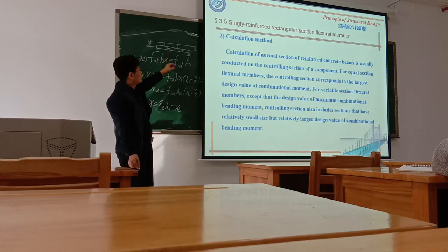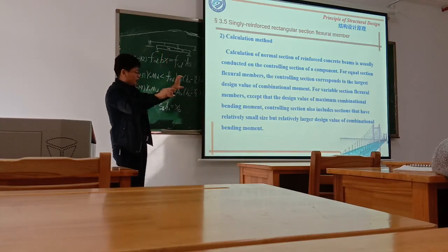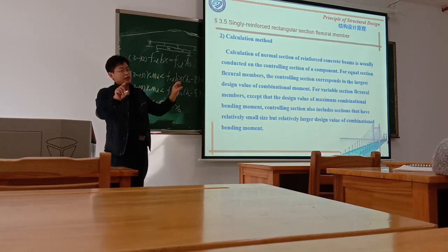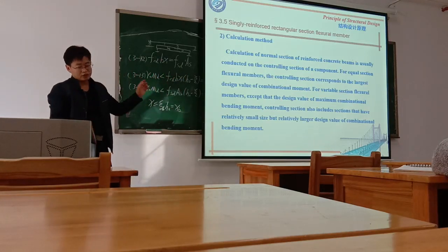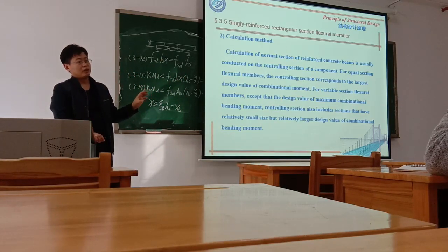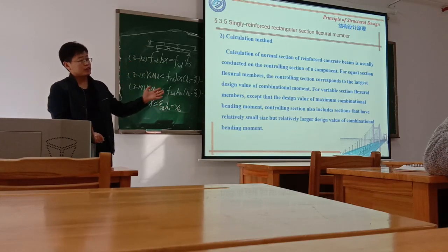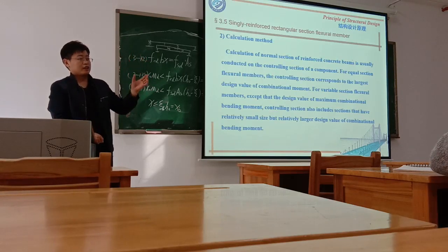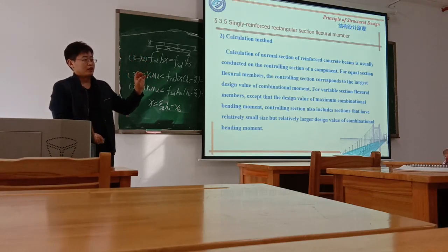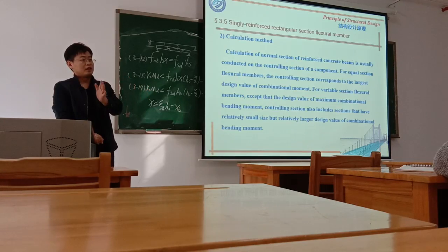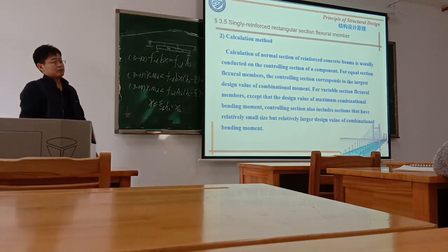In some situations you change the dimension of the section. So it does not only depend on your moment. Maybe at this position the moment is not the largest one, but the dimension of the section is relatively smaller. Then the resulting stress may be more dangerous than at the maximum moment position.